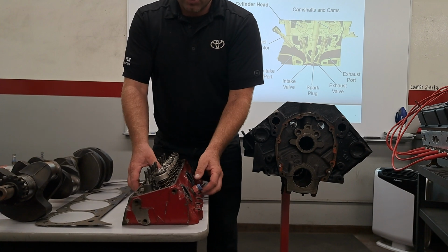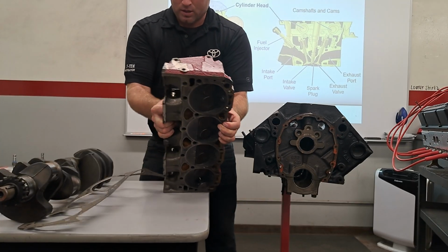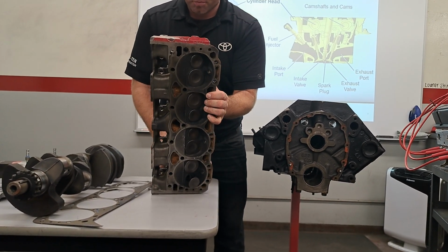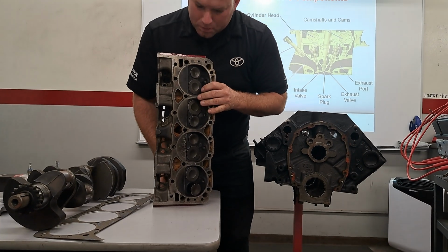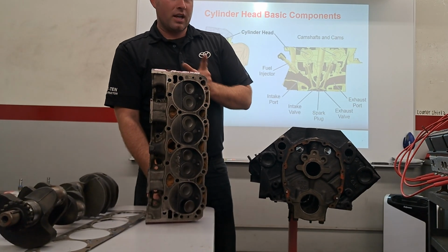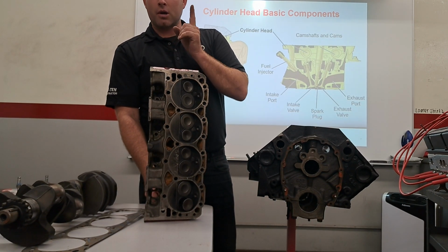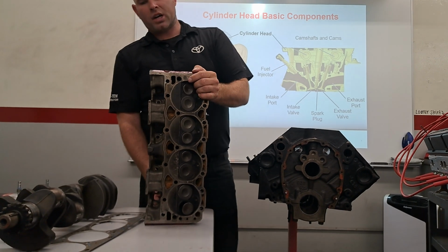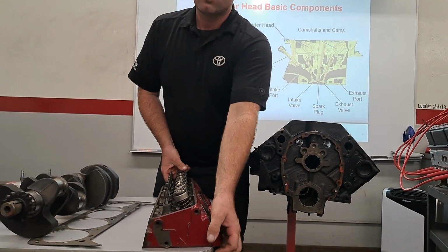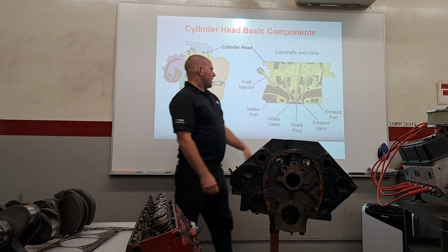If you were to have it stood up like this, these are a lot heavier than they look, by the way. All right, and I'm going to try to not drop the valves. I've got one valve pre-popped out for our lecture. The spark plug is actually coming in at this angle. So not all spark plugs are in the middle, but pretty much the stuff you're going to work on is going to have the spark plug coming from the top. If you work on an old V8 and it comes from the side, now you know it's just a different wedge-style combustion chamber design. Cool.